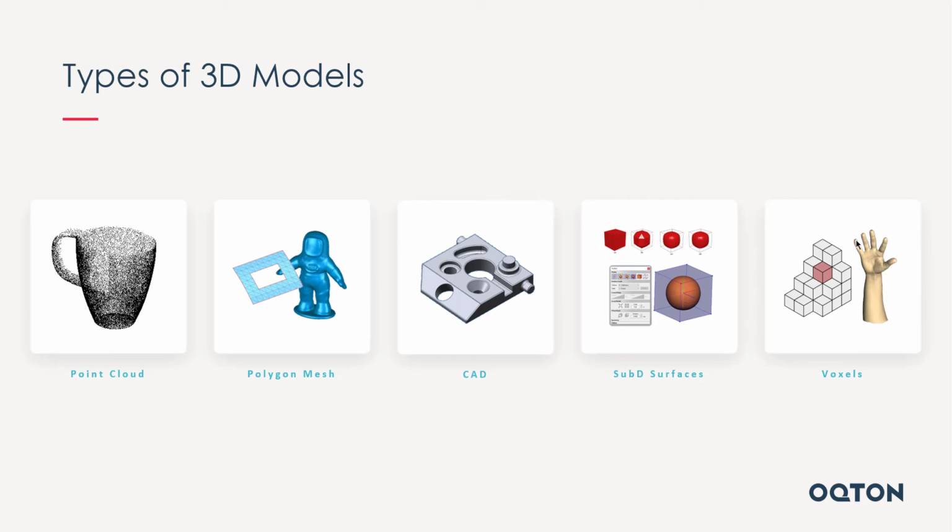This is like the most basic rudimentary version, a point cloud. A point cloud is just a group of 3D measurements, X, Y, Z points in space that are graphed, right? And in this instance, you'll see that those points are all black. But sometimes those point clouds can also have IJK direction vectors as well, which will allow us to shade them more appropriately and make it make a little more sense to look at in 3D here. And then they can also have intensity values, RGB values. There's all kinds of other values that can be on top of those point clouds.